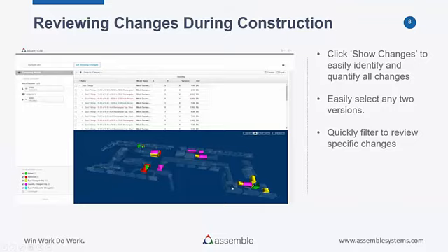But if you're looking at comparing this against the change order, and maybe a bulletin came out during construction and you need to validate what they placed in this change order because things are already coordinated, you're able to drill in and see exact quantities that change between their fabrication models rather than looking at maybe the designer's models and seeing what changed there. This is going to allow you to drill into exactly what changed and what's being fabricated that comes from that model there.